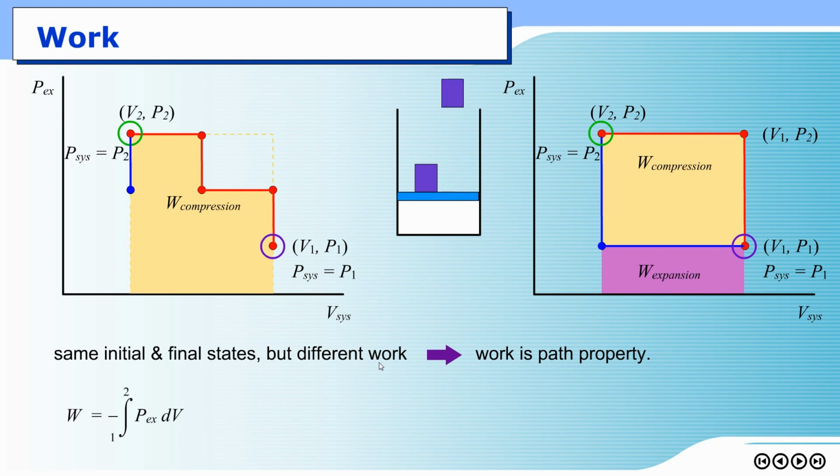Now if I lift 50 kilograms up, the pressure would decrease to this point abruptly, and then the piston would start moving up because the pressure inside at this point is higher than the pressure outside. It will start moving up. Once it reaches equilibrium, you can lift another mass, another piece, and then it starts moving again.